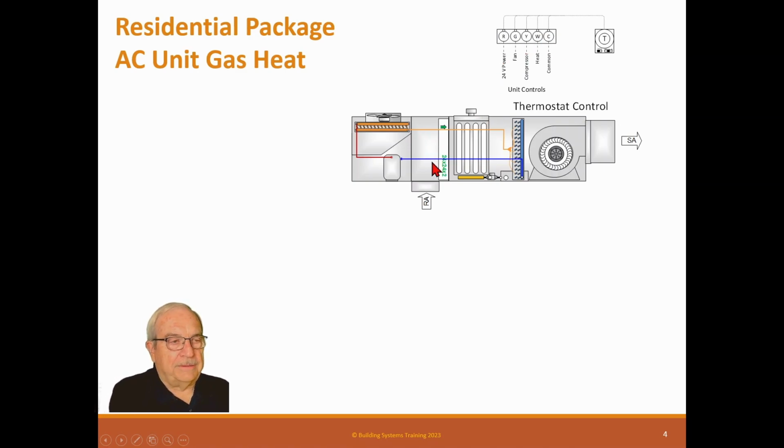Oh, I should mention, there are some manufacturers out there that make AC units, and they also make control systems, like Trane. Others haven't, but Trane has gone so far as to, on their smaller units, basically only have one of their controllers in here. They don't have these lug points for you to land a thermostat on. So you must use a Trane sensor on it, because it's an electronic sensor. It's not a regular stat. However, if you want to put it in a system differently or attach it to a DDC system that's not Trane, then you buy a little module and it connects into their internal network and provides these points. So you can do it, but you have to buy that extra piece.